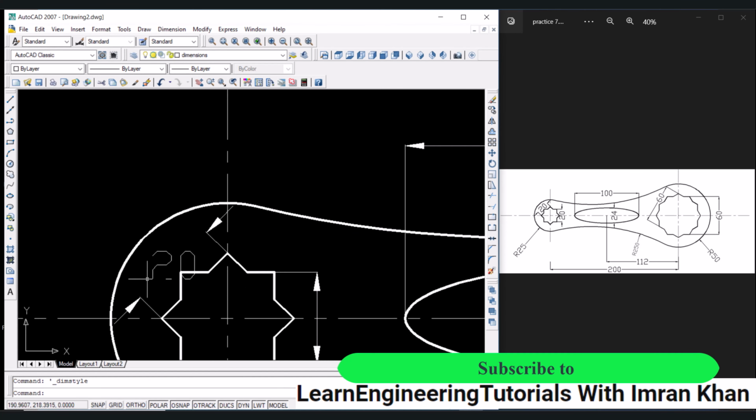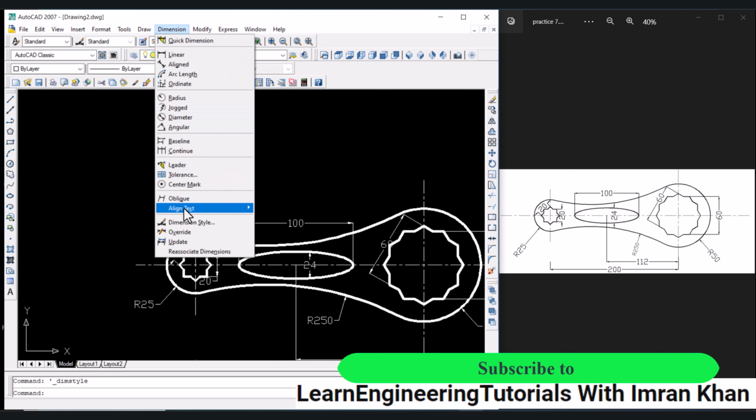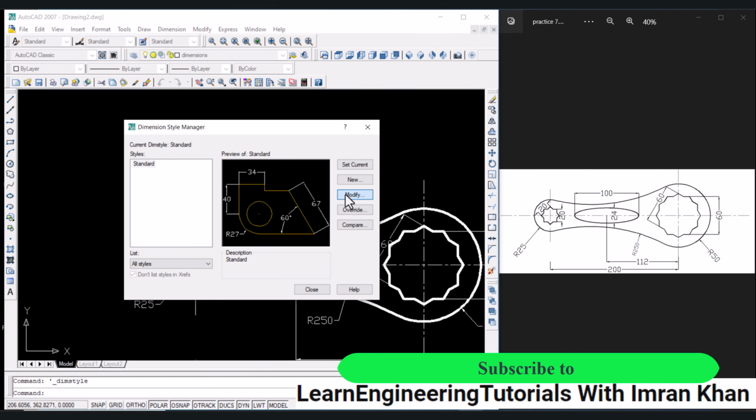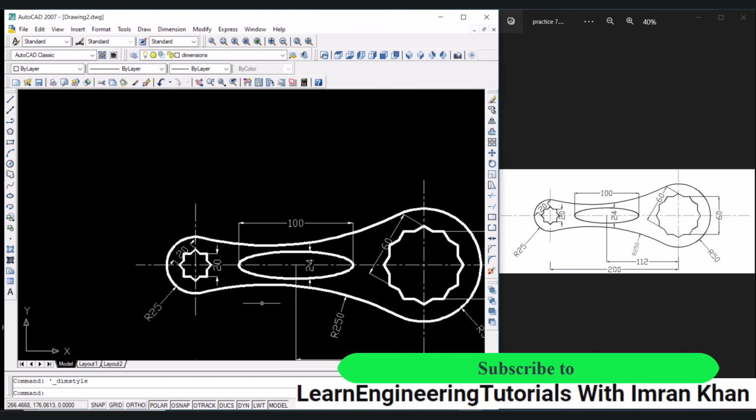Now here we can see that these text should be aligned. So for that we have to go back to dimensions, click on dimension style, click on modify. Now here we have text alignment, so we can select align with the dimension line, click on OK, click on close.